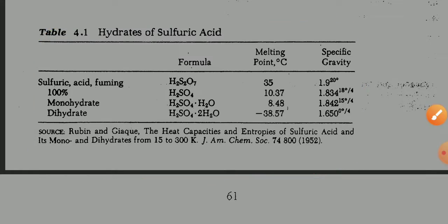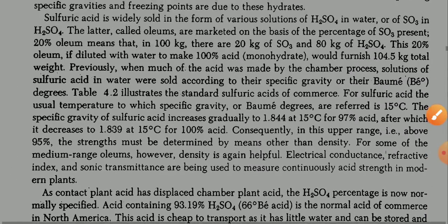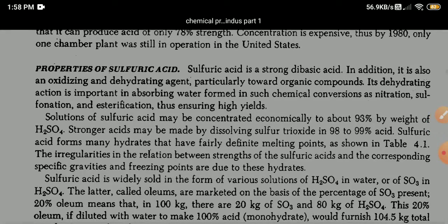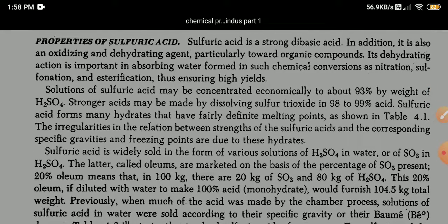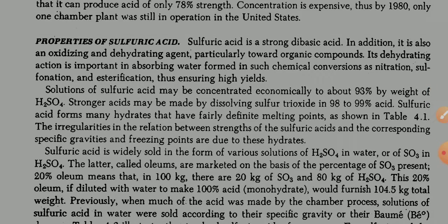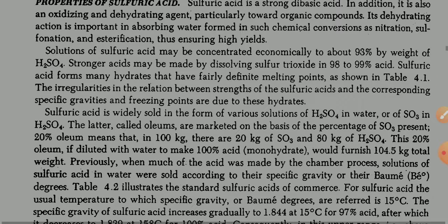Okay, this is important for the table. For the properties of sulfuric acid, the many hydrates are fairly well defined at their melting points. The irregularities in the relations between strength of sulfuric acid and corresponding specific gravities and freezing point are due to these hydrates also.